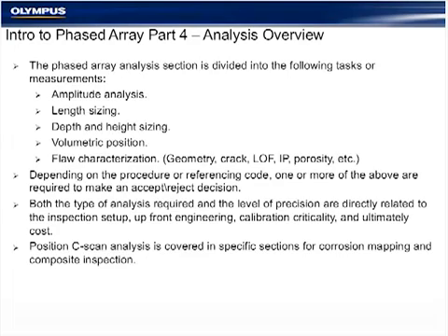In fact, as a service technician working with customers, the overwhelming majority of data I see typically has more mechanical acquisition problems than software or calibration problems. Meaning the probes were not adjusted well, the mechanical carbides on the feet were not positioned well, or some of the scanner mechanics may have been loose.